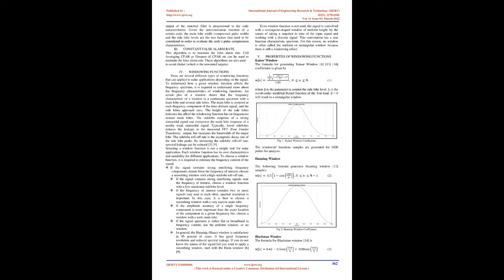The output of the complex multiplication is processed using an inverse Fourier transform. The output of the IFFT, inverse fast Fourier transform, is the matched filtered output. There are three main waveform design techniques used in digital pulse compression. These techniques are linear/nonlinear frequency codes, binary phase codes, and polyphase codes.